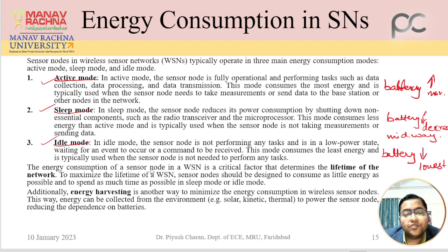So the energy consumption of a sensor node in a wireless sensor network is a critical factor that determines the lifetime of the network. The more residual battery remaining, the higher the probability to survive in a network, and the network lifetime increases. To maximize the lifetime of a sensor node, it should be designed to consume as little energy as possible and to spend as much time as possible in sleep or idle mode.